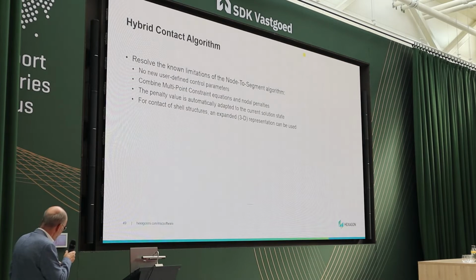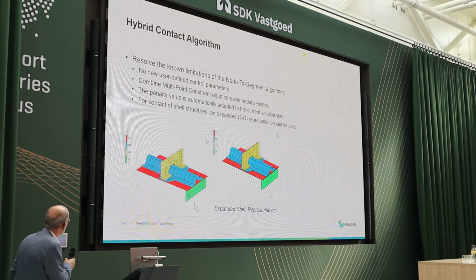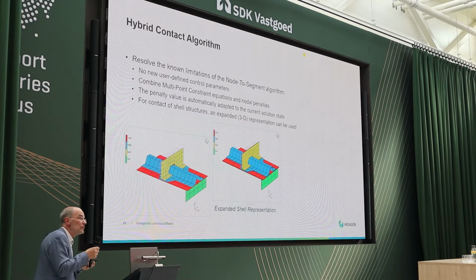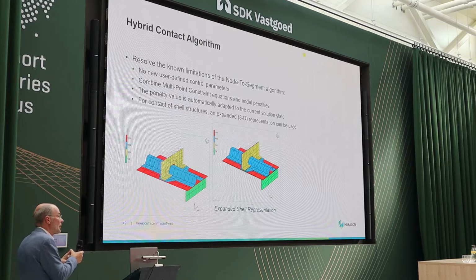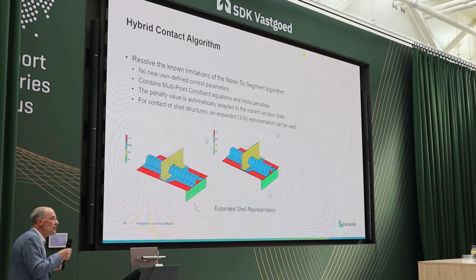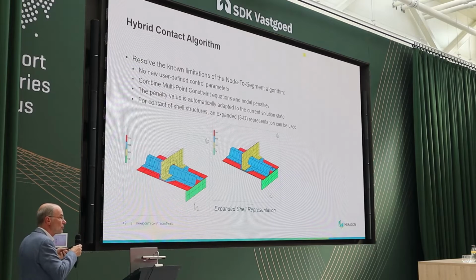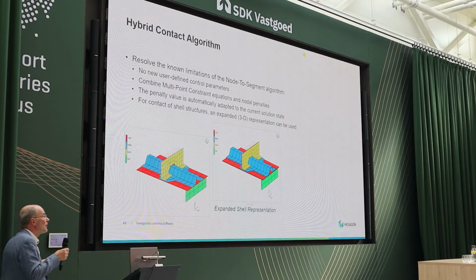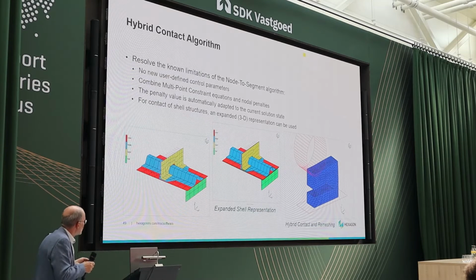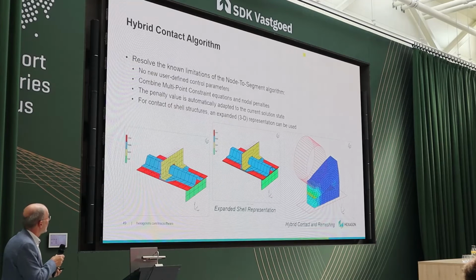And along with that, we have also introduced a new way of solving contact problems with shell elements. Those of you familiar with shells know that we basically model a 3D space based on a 2.5D representation, if you want. And within this finite element simulation, we are now able to reproduce it as a true three-dimensional body, but for contact only. So the actual shell equations are still there and are still being used. So it's only for contact we can use it along with this hybrid algorithm. And I'll get back to remeshing along with contact in one of the next slides.